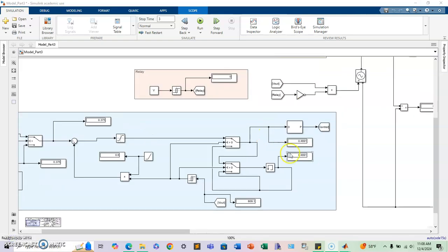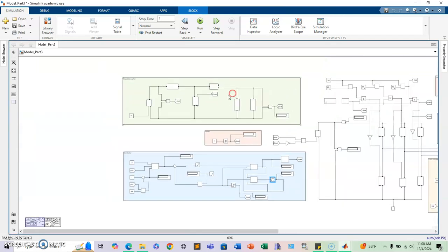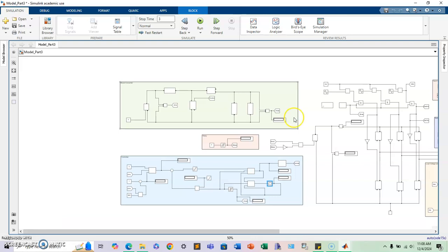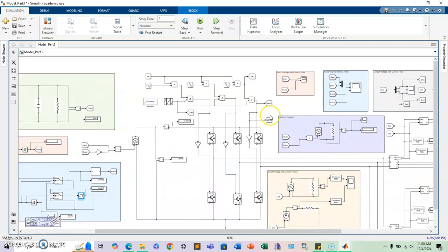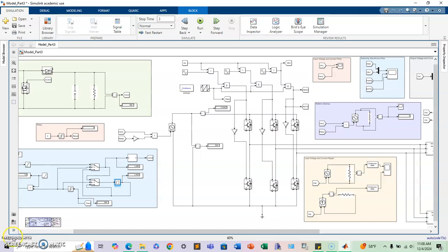Going back to the controller, you can see how right here the actual value switched to the second latch, and right here I have a memory, and it's the last value that's going to the MOSFET that's modulating the boost, and this actually works for all the values. So imagine if you had 500 or even 440 volts, it's going to have the same behavior. The only thing that will be different is if I put a value that's below 350.